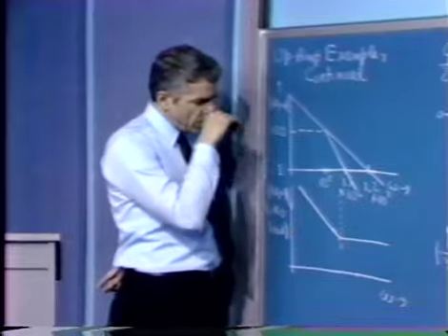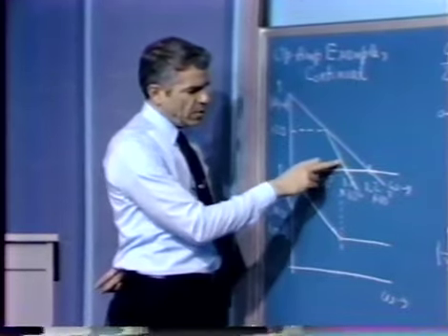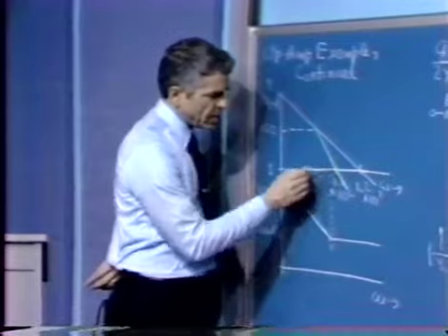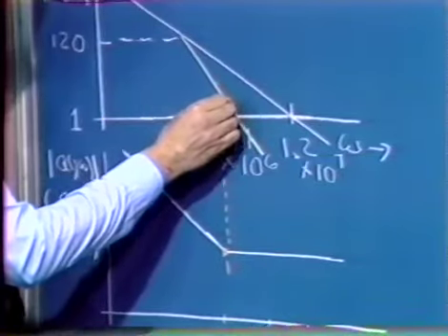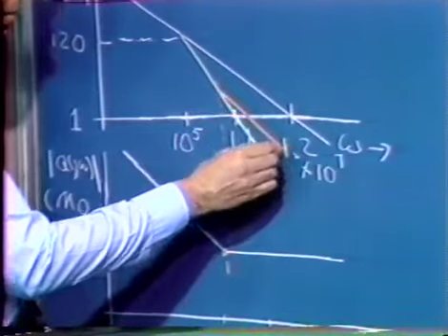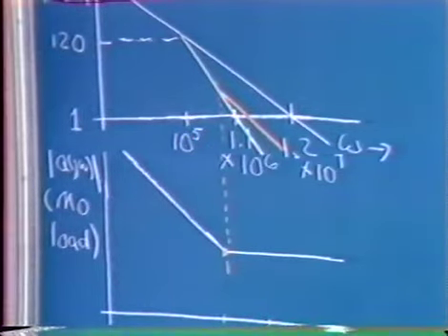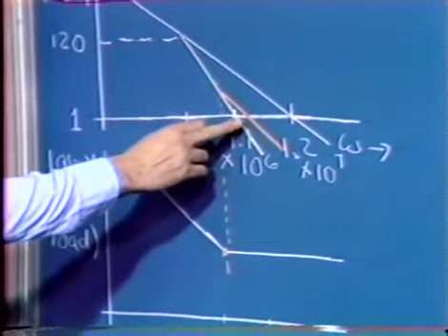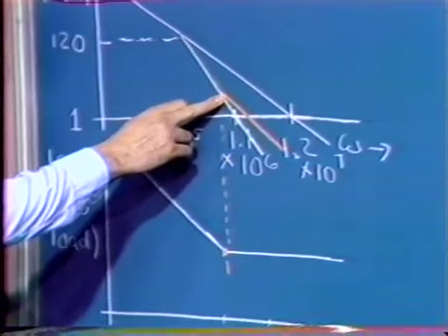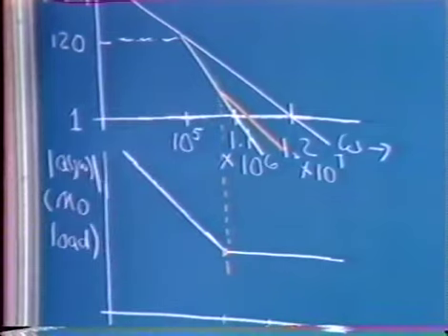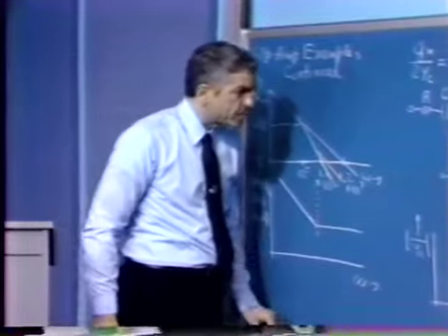We'd use that zero to offset the effects of the pole that resulted from capacitive loading. As a result, our overall loop transmission, or the negative of the loop transmission, might look something like that. The hope is that, of course, we greatly improve the phase margin by virtue of having added this zero to the loop transmission. Let's see how that works.